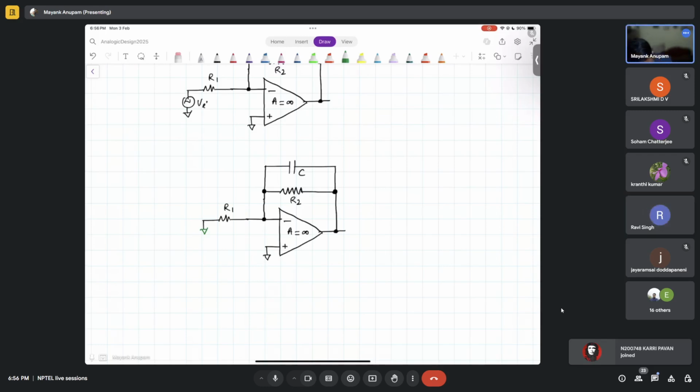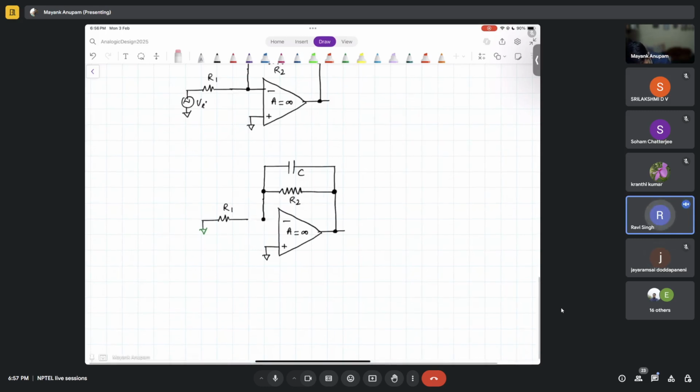Yes. So that is the next question. Where do you think is most beneficial to break, such that it becomes very easy for us to analyze? Probably the input of R and C, wherever it is connected to. Good. So we will break it here, and then we'll apply a test voltage, right? We apply a test voltage here, and what do we have to look for?